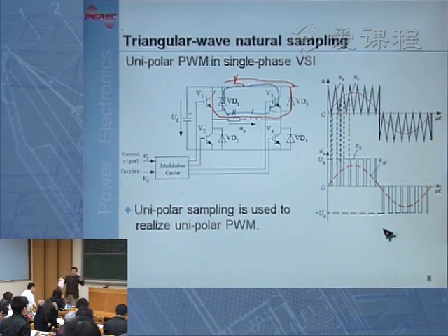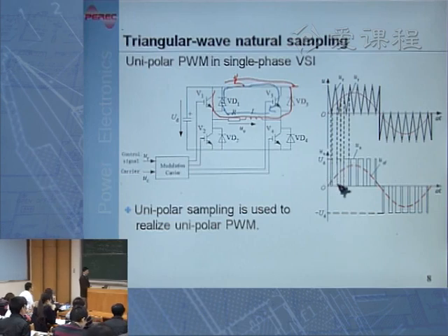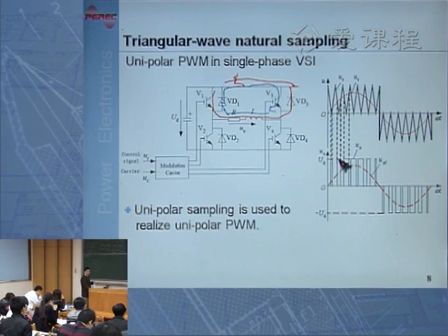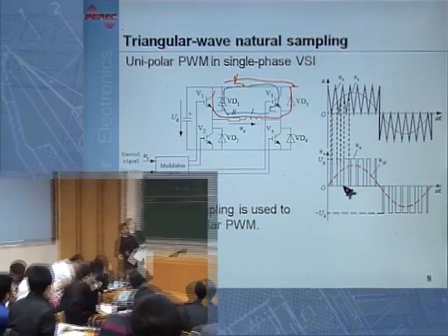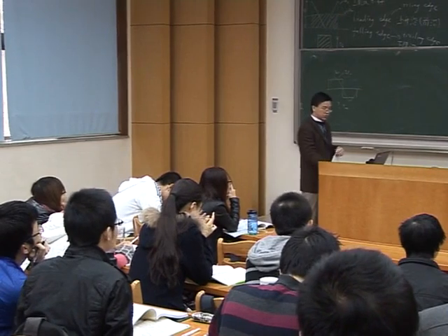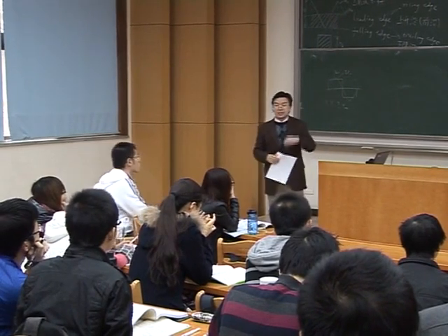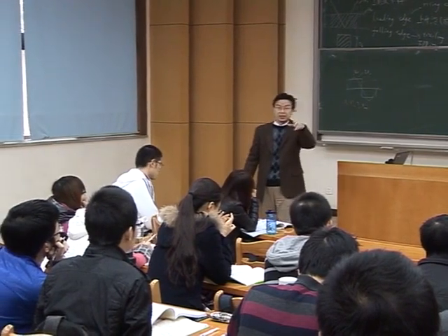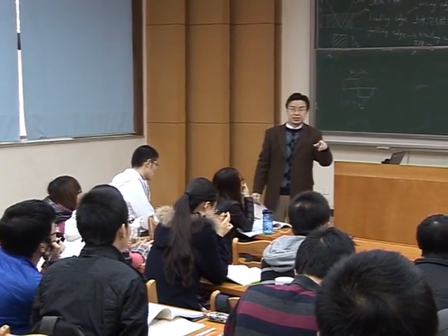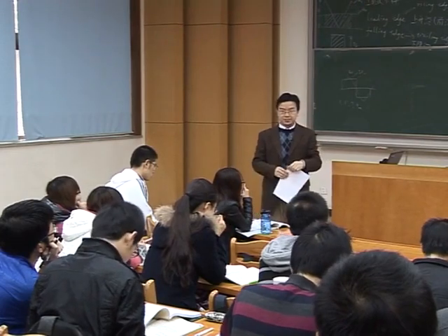So far, we have always been talking about when this happens. At this instant, we want to turn on V1, V4, and send a turning off signal to V2 and V3. And then for this section, when we want to generate 0, we said we can send a turning on signal to V1 and V3, and a turning off signal to V2 and V4. This is all the idea. And how do we automatically implement this idea in a control circuit?